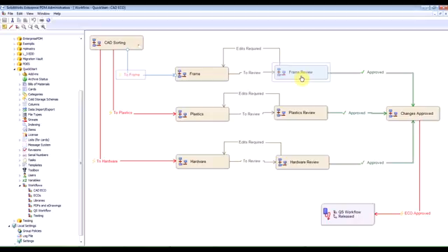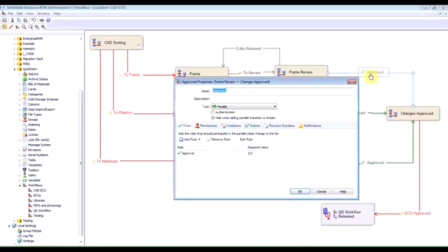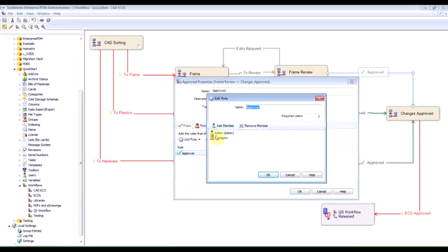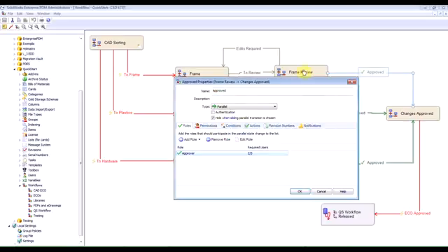And then files will sit in this review state. And from there, we have this approved transition that is parallel. And remember, when you select parallel, you can add the role and determine what groups or what users are in that role, and how many are required out of the total number of users. So you could have 1 out of 3, which really doesn't make sense, but at least 2 members, so you can have a parallel approval. So have 2 or more people approve a drawing before it actually moves through that transition.